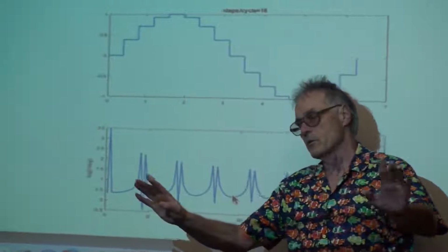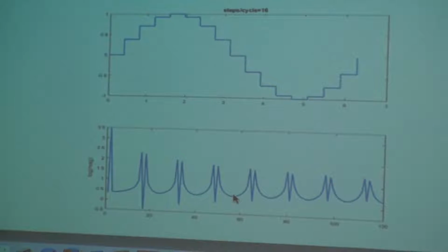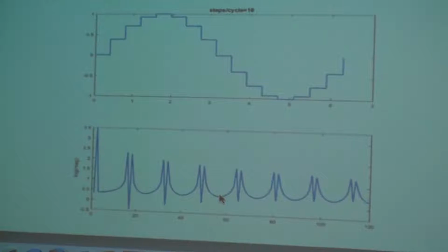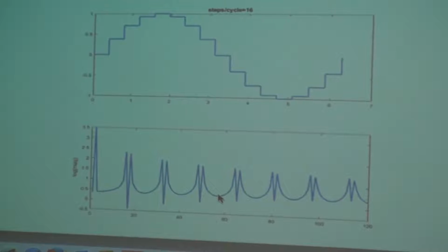Let me remind you that questions 1 and 2 interact. If you sample fast enough, you may not need a filter at all. If you filter enough, you may not need a fast sampling rate. So your answer for 2 depends upon your answer for 1.